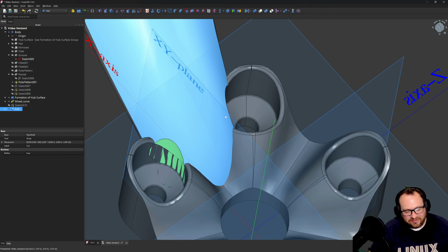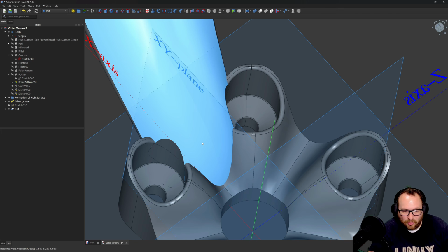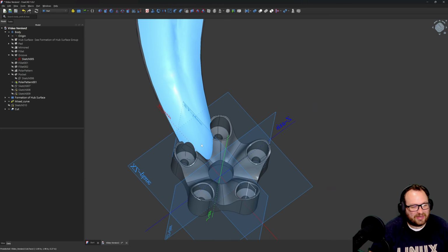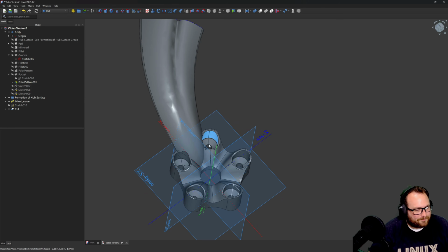That's on both sides of the spoke. So if we have a problem, one of the big things, especially with Open Cascade, is look for these kinds of possible zero thicknesses. If there's a problem, we'll increase the size of that revolve that we've done and subtract more of our spoke, and that should take care of any Boolean errors. For now, we will call that good.